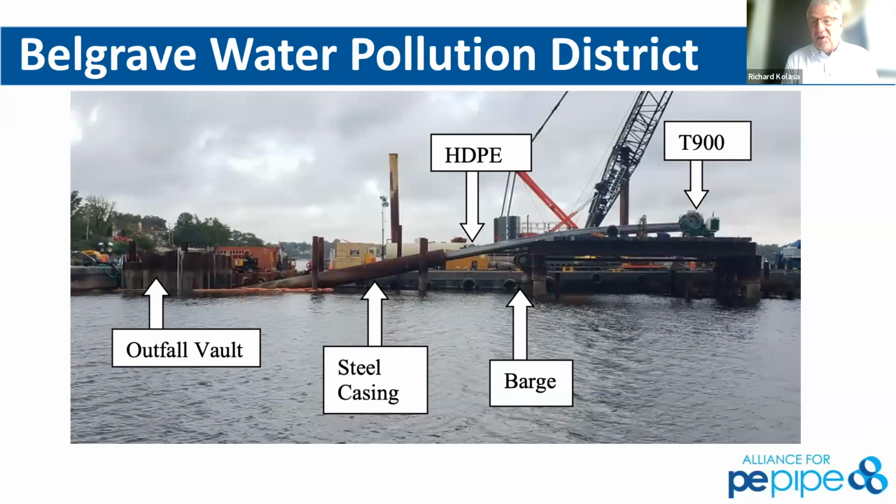The hardest part, believe it or not, was just fusing the pipe together on the barges, because we did 200-foot sections, and then we joined the 200-foot sections to make the total length. And that was the biggest challenge, just because of safety, wind, all kinds of weather conditions out there where you're completely exposed. Drilling it in was really, really good.